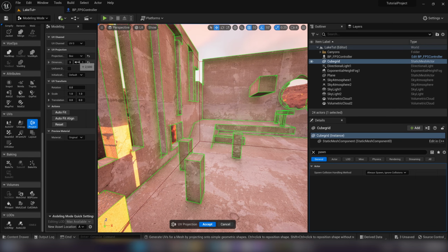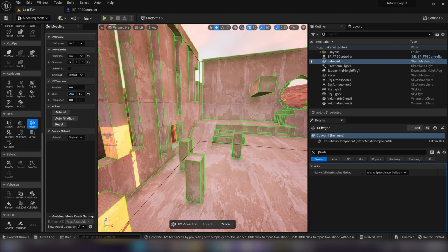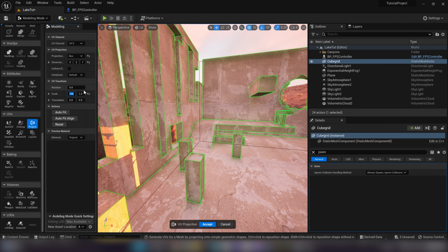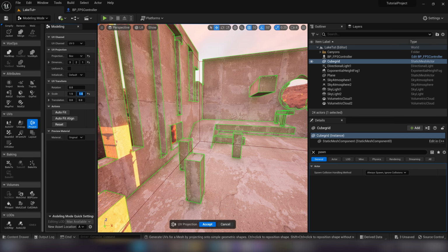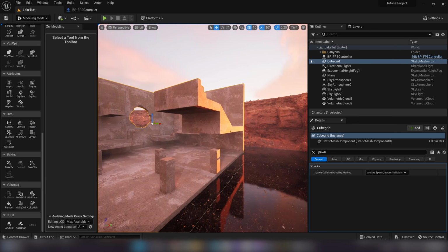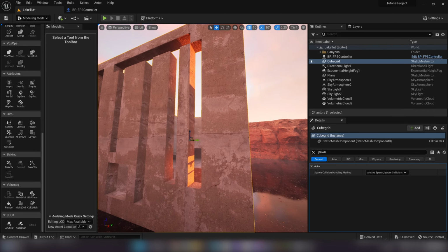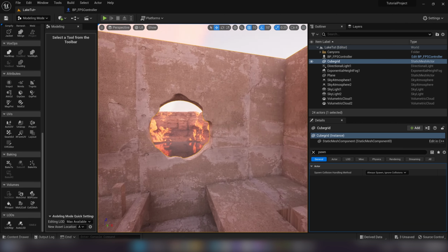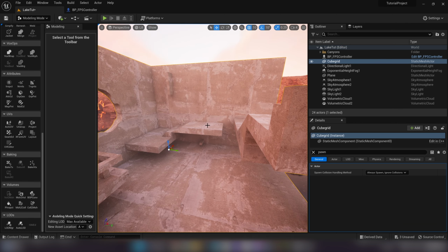And then we can also change our scale here, so we can rescale that one. So I think about a 1.5 scale is looking pretty good. All right, great. So I'm going to accept that. And that just means that we've got pretty even texture UVs, and we didn't have to go in and change the actual tiling on the texture. So if we were using that texture in multiple different contexts, we haven't gone and adjusted that material directly.